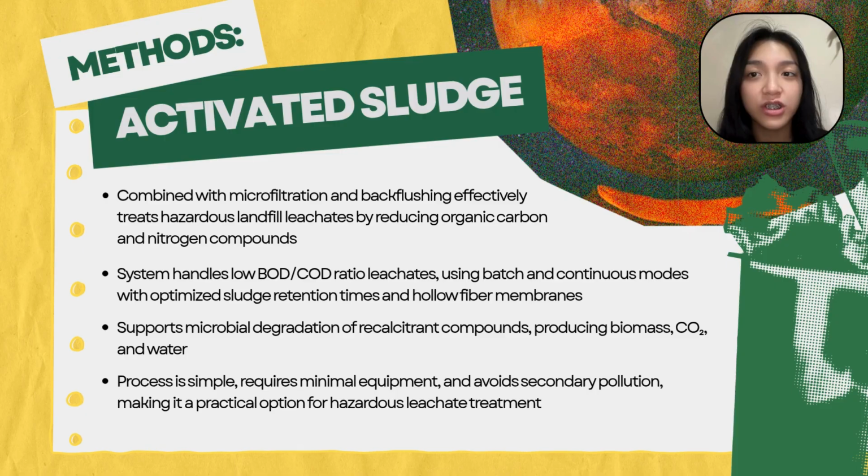To improve efficiency, microfiltration membranes with a backflushing technique are used. Backflushing periodically cleans the membranes, prevents clogging, and maintains steady filtration. This setup allows for better control of sludge retention time and supports the microbial community needed to degrade the stubborn organic pollutants.